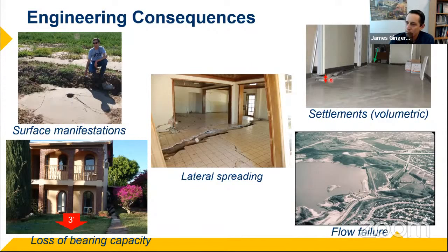Over here, the slab was right at grade, so it didn't have any treatment of the slab, and the slab settled. So you can see the slab settled about 6 inches. The building structure itself was just fine. It was supported on piles and didn't undergo really any damage, but the whole ground floor had to be demolished because of the slab settlement.